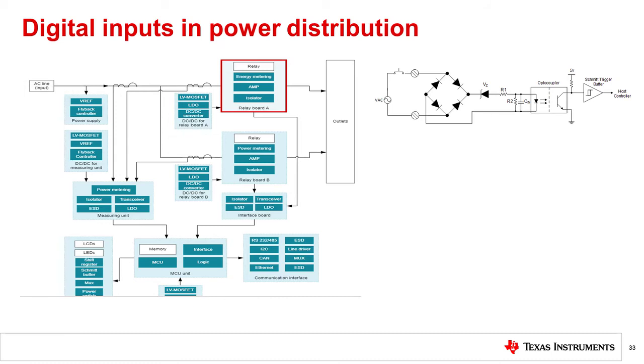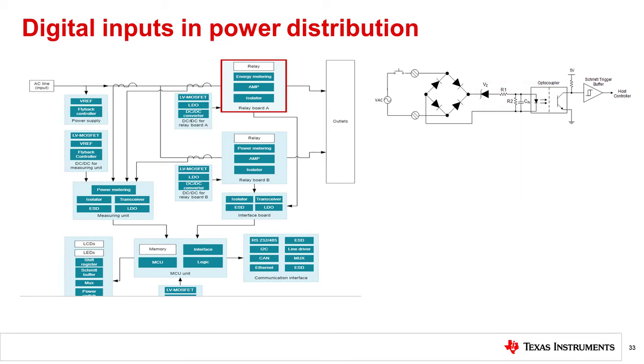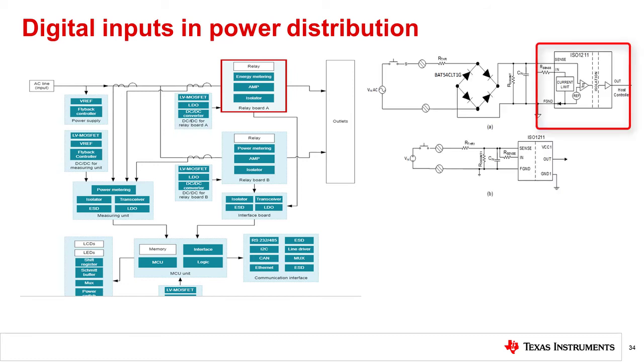A full bridge rectifier would rectify the AC voltage into DC, and a Zener diode ensures that the optocoupler receives input current only beyond a certain voltage, which roughly creates a threshold control. The addition of the 2 resistors R1 and R2 provides some voltage control while limiting the input current. This same circuit could be used without the bridge rectifier for DC detection as well. So why would this circuit be designed any differently today?